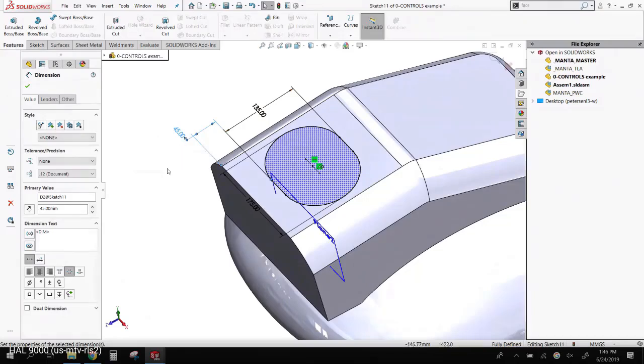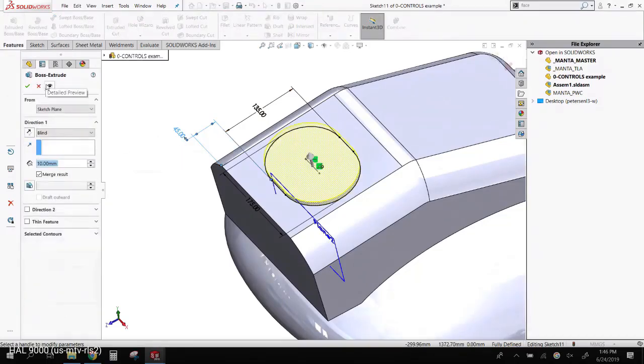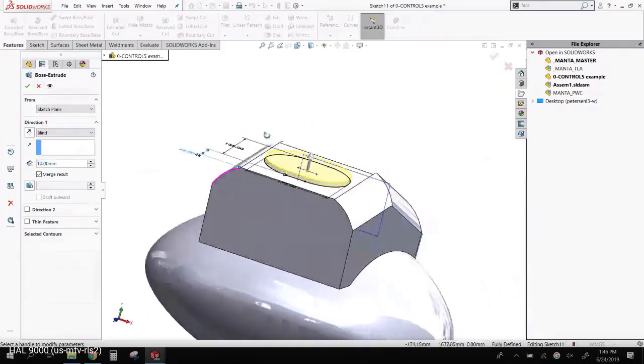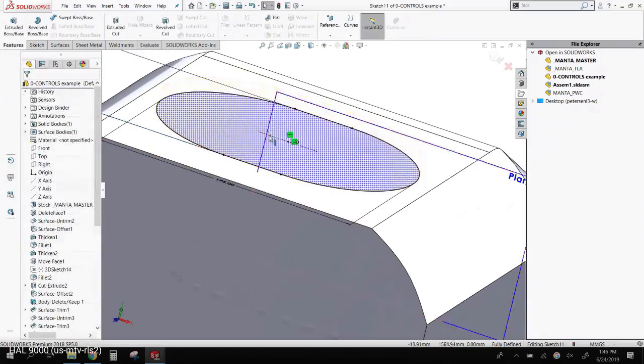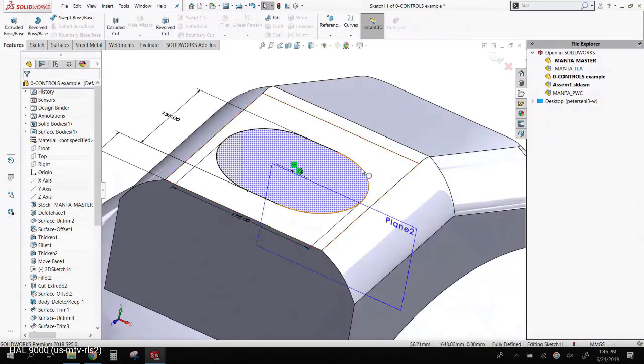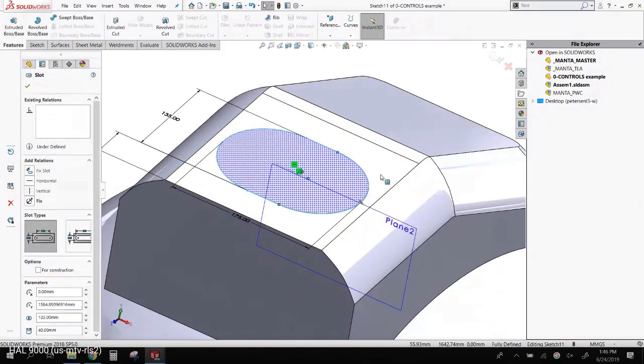I want to extrude this out, but I want to make sure that it's a really smooth extrusion that I get. When you're doing a slot, you've got 4 items. You've got 2 arcs and 2 lines. And automatically, it's going to give you a tangent line where those 2 meet, giving you 4 faces around it. I want to have it as just one single face. So what I can do with that is first I'm going to right click on this thing, say select chain. That'll give me whatever loop is there.